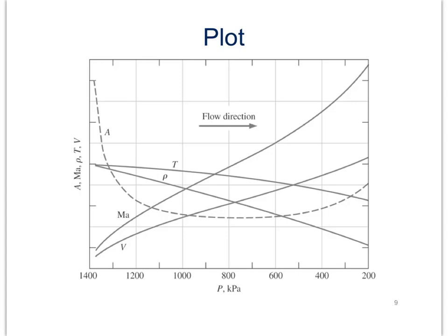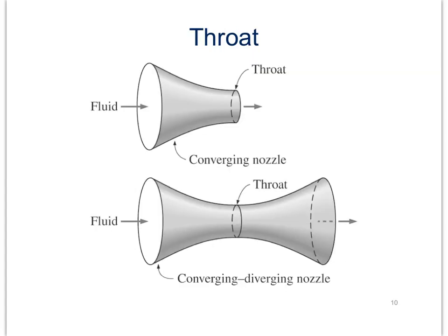There's something I want to point out about that. As we saw in the figure, we have a converging-diverging nozzle. It works as a nozzle the whole way because the area decreased, then increased, but the Mach number increased up to 1 at the throat and then continued to increase past the throat. When that happens, the throat is the point at which we have sonic conditions, where the Mach number is equal to 1.